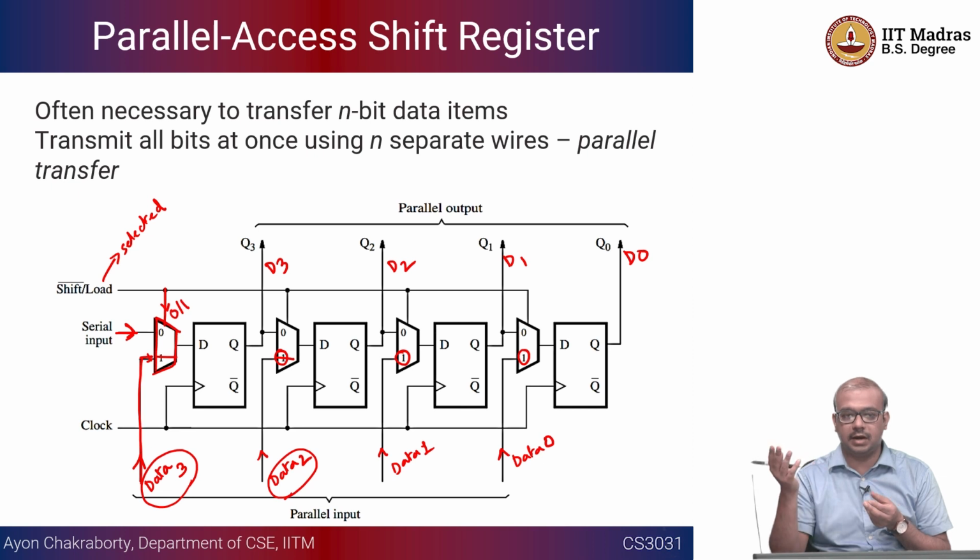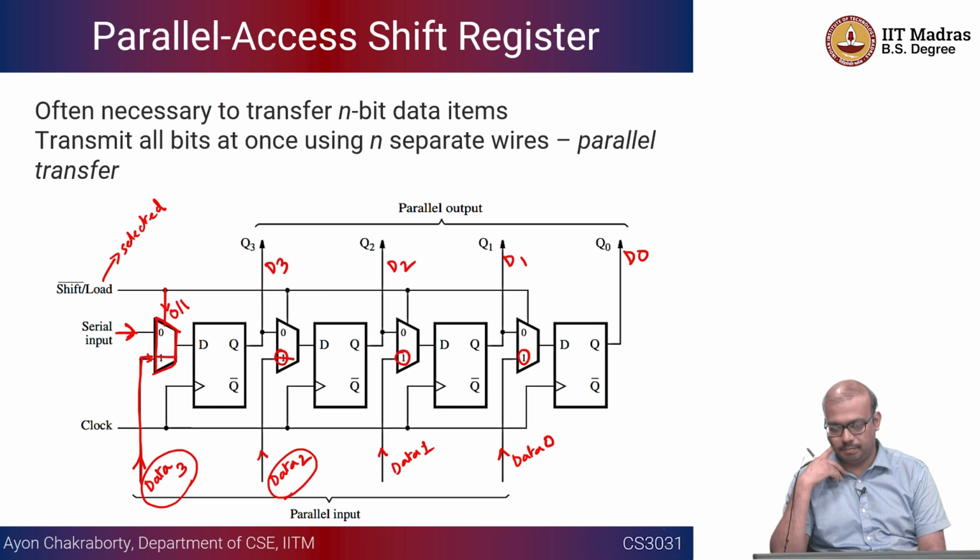Let's say you want to connect or propagate the value of a particular flip flop to the so-called left hand side flip flop; it basically becomes a left shift register. Okay, so left shift or right shift: right shift is useful for division kind of purposes, whereas left shift will be used for multiplication, right? Multiplication by 2, and right shift will be division by 2, right?